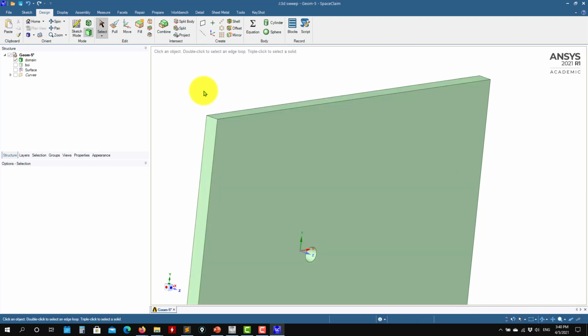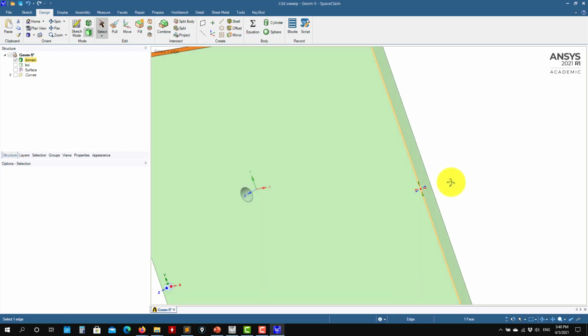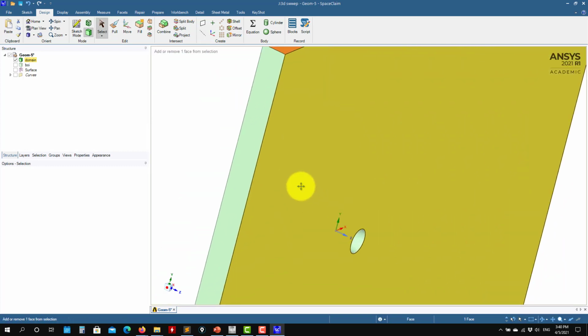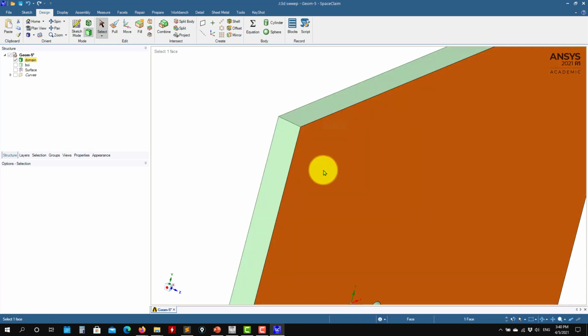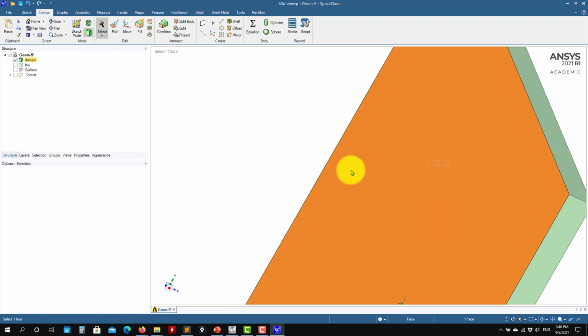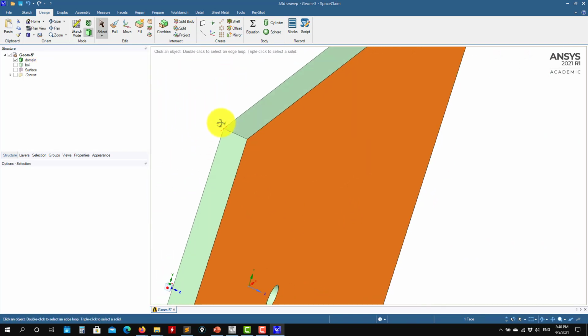So there is no difference. The only difference is that for boundary conditions, you are going to create name selections on surfaces. When you do the mesh, you have to be careful that you need to use an extrusion, a sweep method, but using one cell here. We're going to do it, but also when you set boundary conditions, you are going to have these two faces, and you need to set them as symmetry, and that's all.